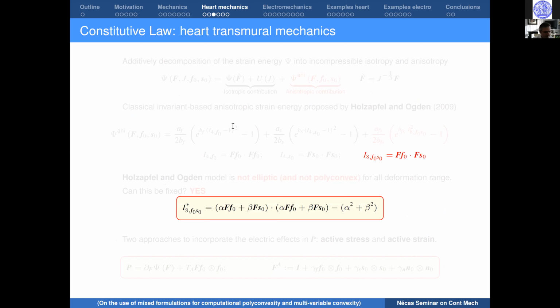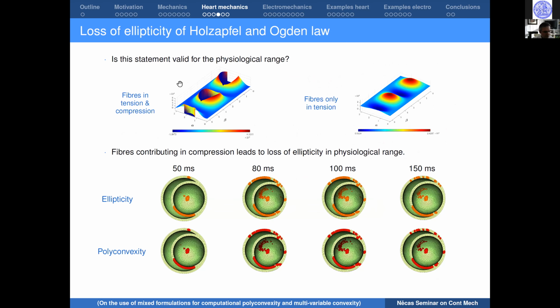However, when you do that, this is what happens: sometimes the acoustic tensor gets ill-posed. It doesn't get well defined. You can see the strange representation that it takes. Whereas if the invariant is activated appropriately with this Macaulay bracket, you can see that now it's very well posed, the shape is very good. And then what happens is that as you refine meshes, you achieve convergence, which otherwise you don't for the first case.